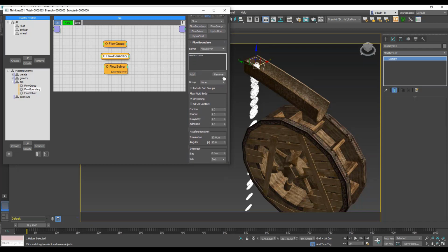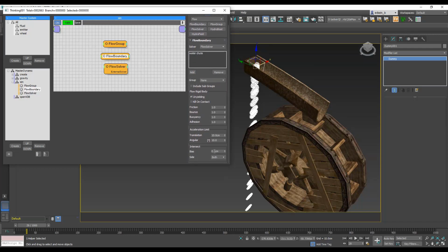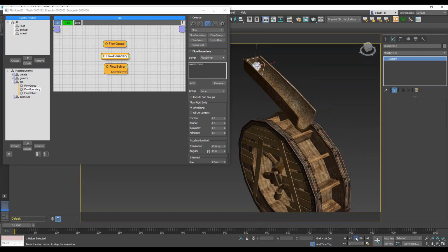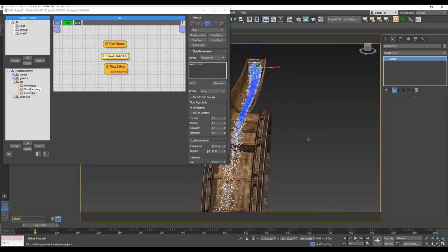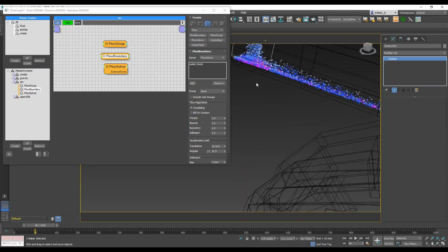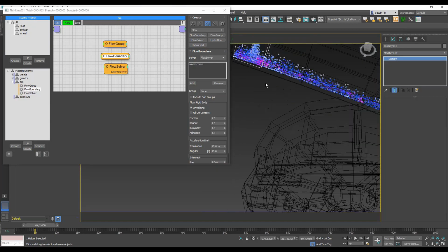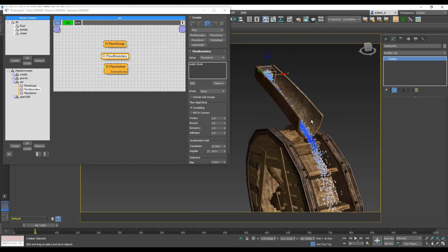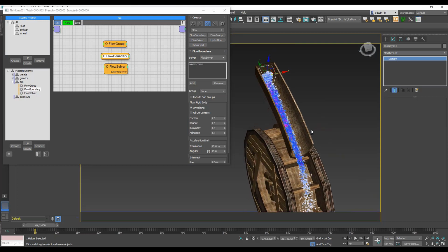And that's actually it. We might want to adjust our bias a little bit for collision detection, and that's it. We're pretty much done. So if we go back now and start to simulate again, we should actually see a fluid. And this is what's happening. So now our particles are no longer falling through, as we can see. And we can see on our pressure display, we actually have a fluid and not just particles falling down.